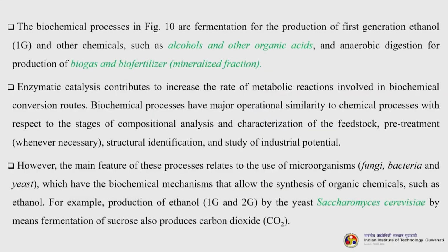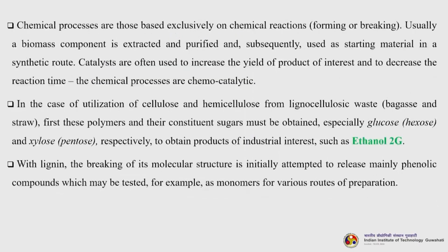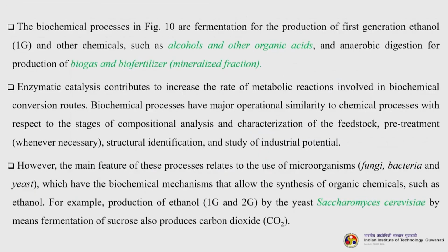So, the biochemical process in figure 10. We will just go back to figure 10, this one. These processes are fermentation for the production of first generation ethanol and other chemicals such as alcohols and organic acids, and anaerobic digestion for the production of biogas and biofertilizer, that is the mineralized fraction. Enzymatic catalysis contributes to increase the rate of metabolic reactions involved in biochemical conversion routes. Biochemical processes have major operational similarity to chemical processes with respect to the stages of composition, analysis and characterization of the feedstock, pretreatment whenever necessary, structural identification and study of industrial potential.